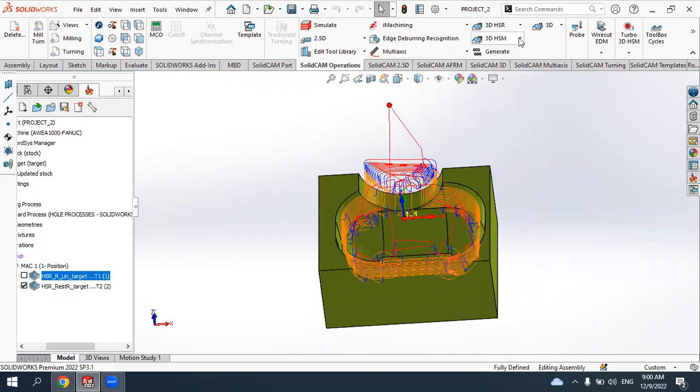So in conclusion, we have seen some basics for the roughing operation. The most commonly used is this one, that's just the roughing. But we can also use contour roughing or offset roughing. Again it's roughing, but here with several different toolpaths. Here we have the zigzag, and here we have the contour toolpath.